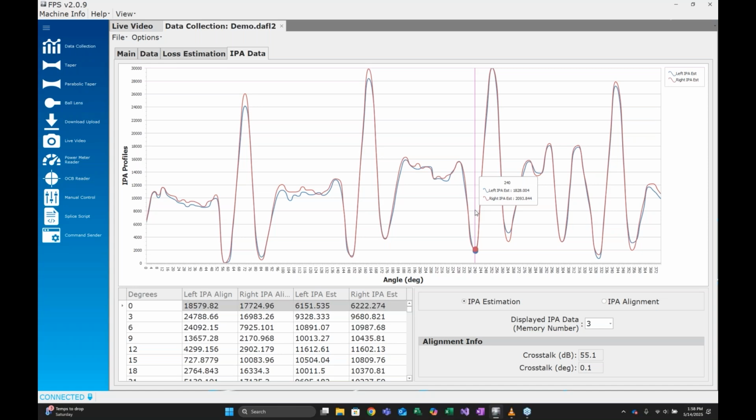What you could do, and this would be very time consuming, is strip some of the fiber behind the fiber holder and then recoat that specific spot, or find some sort of polymer or acrylate that has the correct refractive index to function as a coating, but also is transparent, so that light can be injected through that new coating and into the cladding, so you can get an end view image.